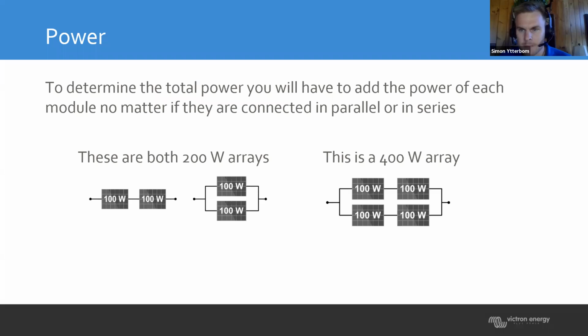It does not matter if we put them in parallel or in series as far as the power production, but put them all in series, because at that point we are getting the voltage up higher, and when we are increasing the panel voltage, we are starting our solar charge controller earlier.